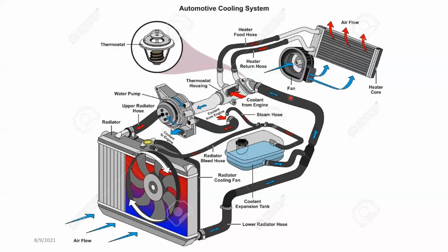In addition to that, there is one small change in a very modern, very new coolant system, and that's the water pump. Previously, as I told you, water pumps were driven by a belt. Nowadays, water pumps are electrically driven, right? That means there's no belt. It will be an electric motor running the water pump, and also there's no thermostat valve, since the water pump is electrically controlled. The thermostat is also not necessary, as the water pump can switch on and off as necessary.